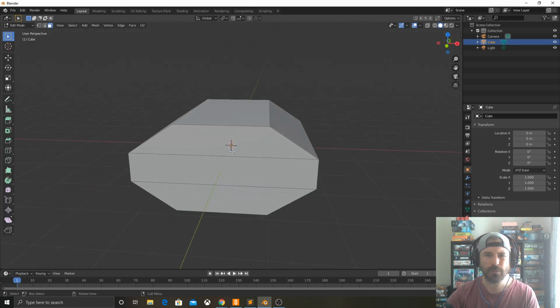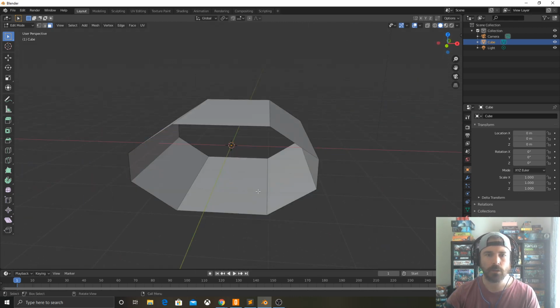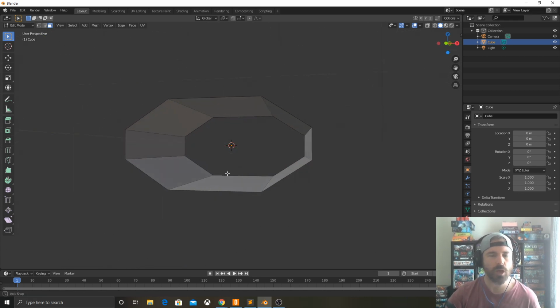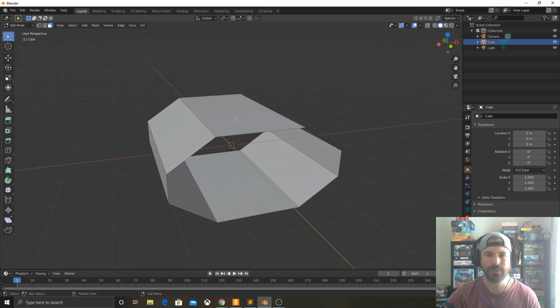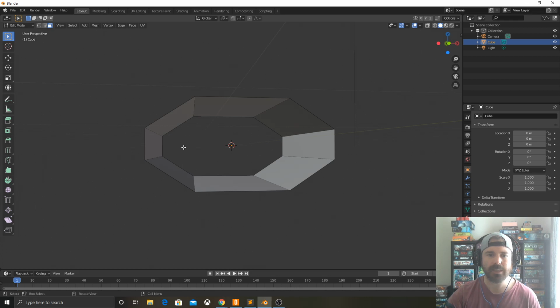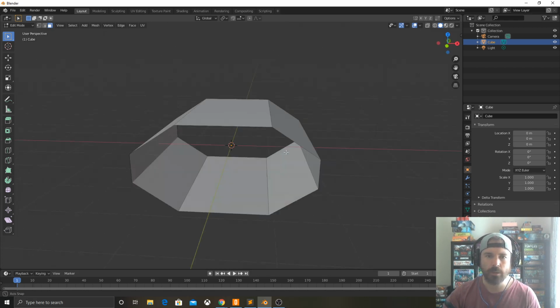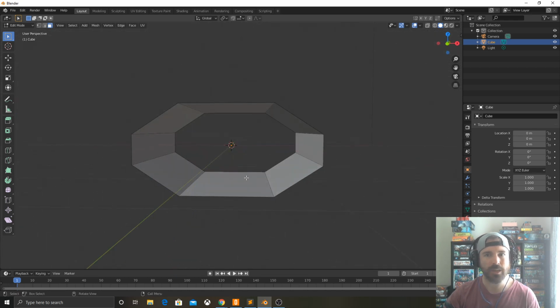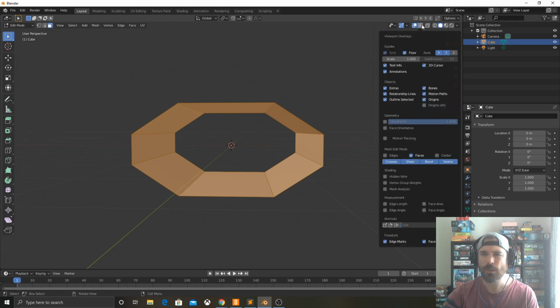Delete those faces. And I need to make sure that the normals are correct, because currently this is the outside of the shape. This is the inside. And if I bring that into Unity or Godot, this won't render, only this will. But I actually want it the other way around. So very easy to do. Select these. I'm going to turn on the normals, which is this button up here, and then down the bottom here I can turn that on there, and I can turn those up.